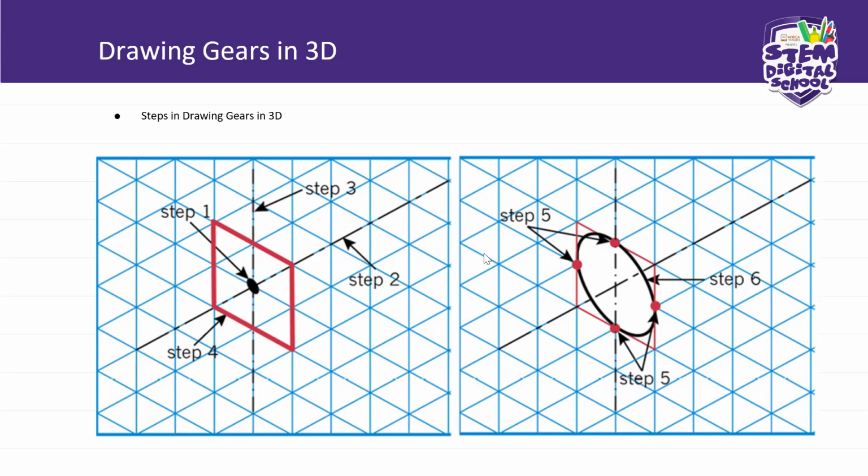The next step, you start by locating the center point. This is your center. And then you draw this construction line, although it's a broken chain line here. And then you draw another broken chain line vertically like that. So it's more like your square face, just facing to the left. It does look like it's facing to the left, doesn't it?